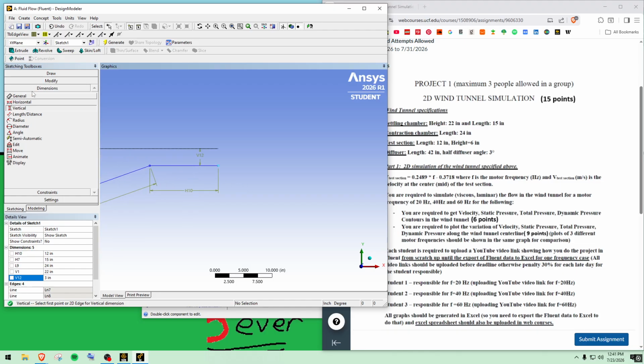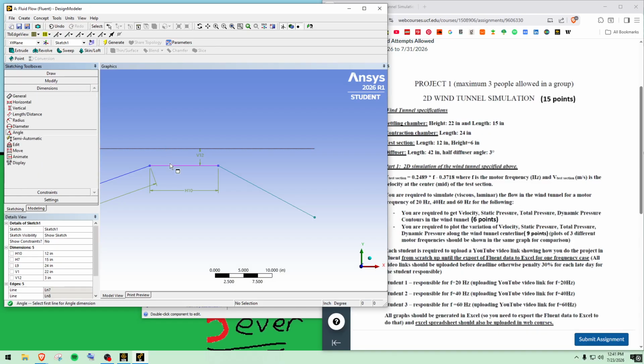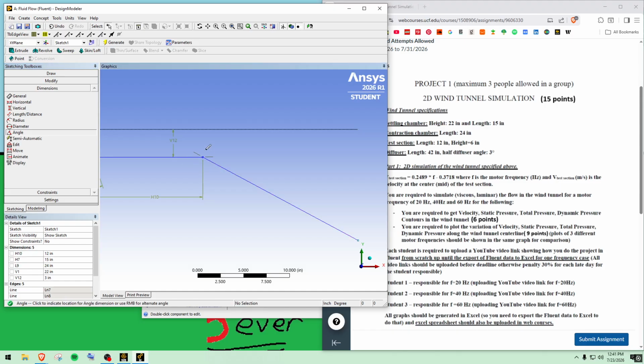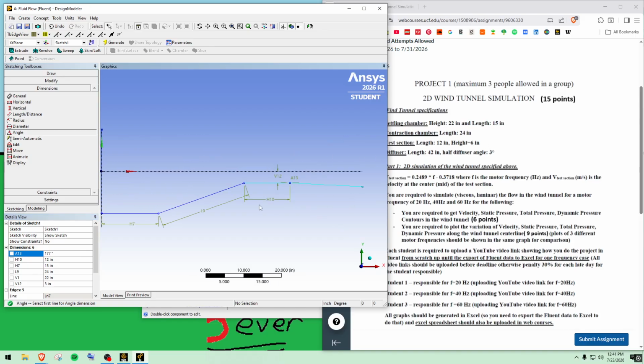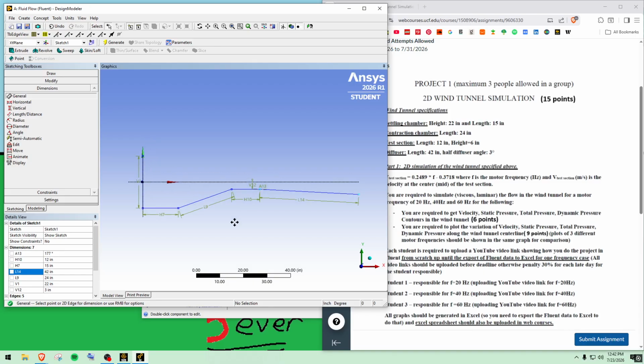But then for our diffuser, we do get an angle. Just going to do that. And then we're going to take our dimensions and do an angle. I like to do the outside, get those little lines in there. We get a 3-degree angle, so 180 minus 3 is going to be 177 degrees. There we go, just a slight angle. Then we're going to adjust our length to 42. And that should be it, at least for our lower layer.